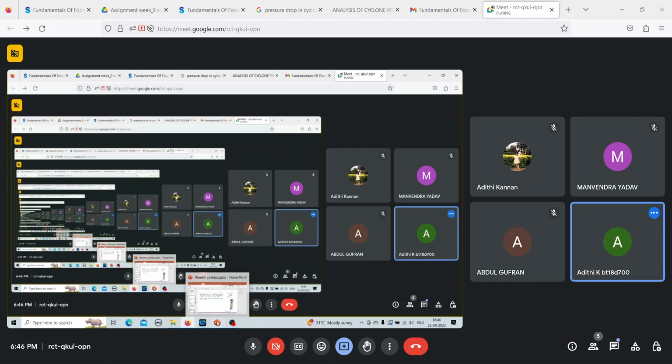So now I am integrating this from 0 to P on the LHS, and on the RHS I am taking from Ri all the way to capital R. When you are centrifuging a liquid, there will be a small region at the center where there will be no liquid present, because everything is thrown towards the walls of the centrifuge. So your liquid will actually be present only from Ri to capital R. The rest of the region will be void. This Ri will be very small, but still we have to consider it. So since the liquid is present only from Ri to capital R, we will be integrating from Ri to capital R.